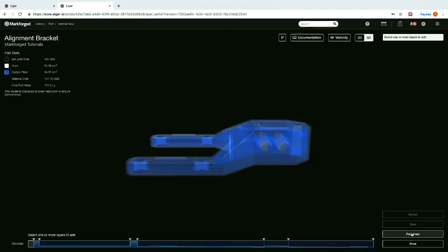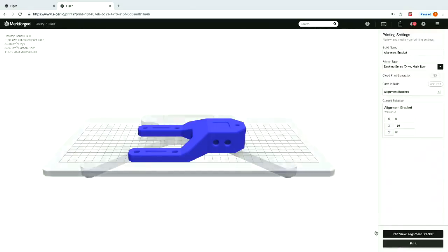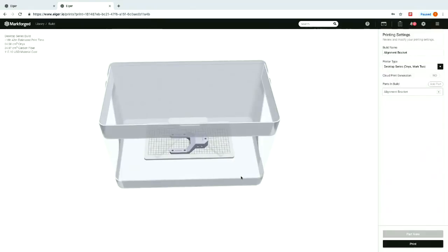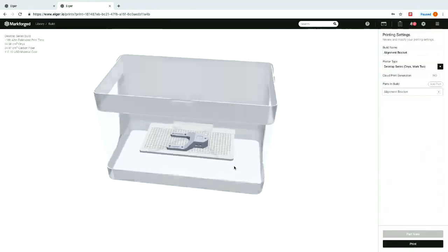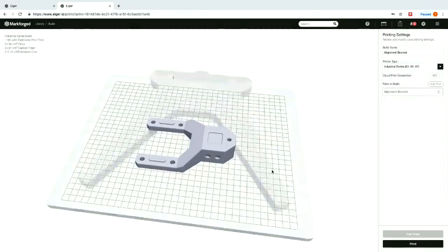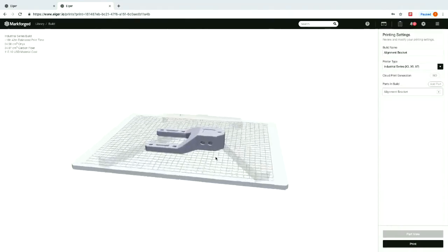So this is kind of a base fiber view going through that. Once you have decided on your fiber, and you see here the same print time and cost estimations, you can go to print, and what it does is it basically changes from the fiber view to laying it out in an actual print bed on our machine. In this case, this is the Mark II. The cool thing here is that even though I sliced this with the Mark II in mind, I could also print this on the X7. Same thing works here. So you can see it in the actual build as well.